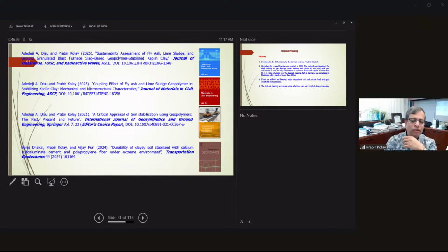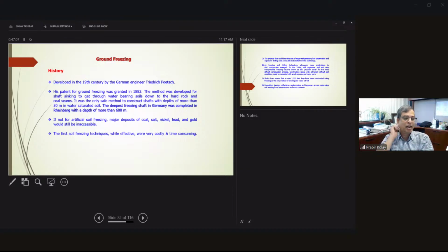Okay. All right. So now the last topic I'm going to talk about, but again, I'm not going to discuss in detail, is the ground freezing and ground heating. Mostly the ground freezing was developed in the 19th century. So basically, if the water table is too high, or water content is there, you just freeze the whole ground, and then do the excavation and construct something on that type of soil.